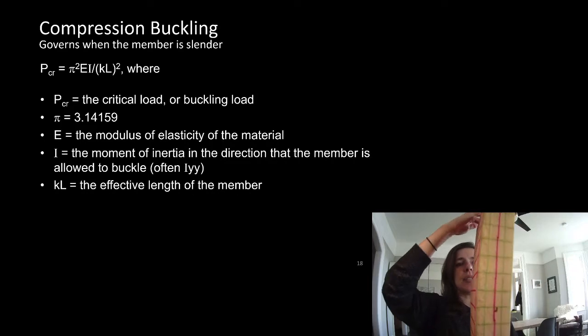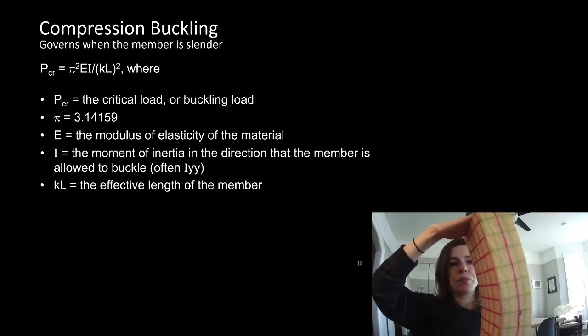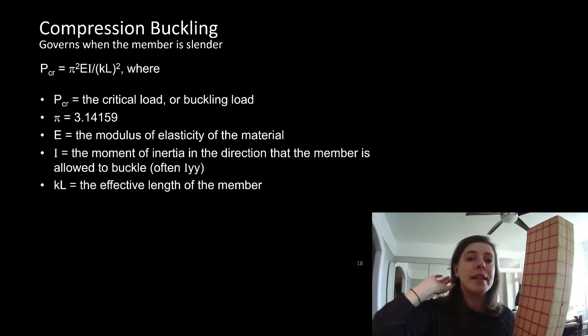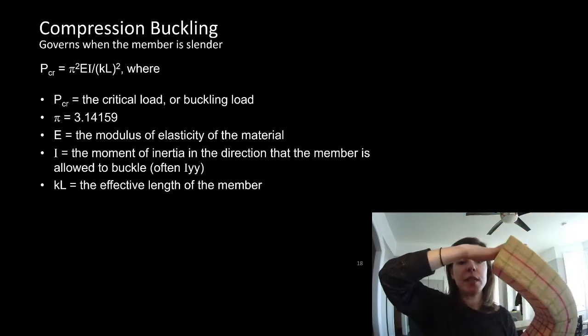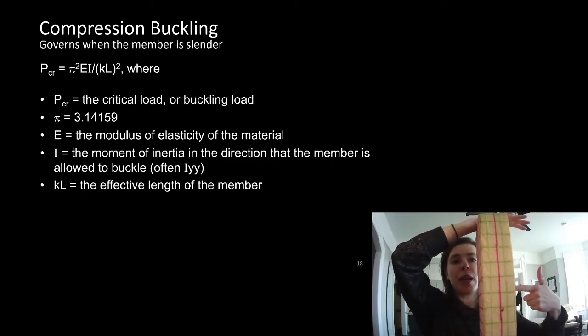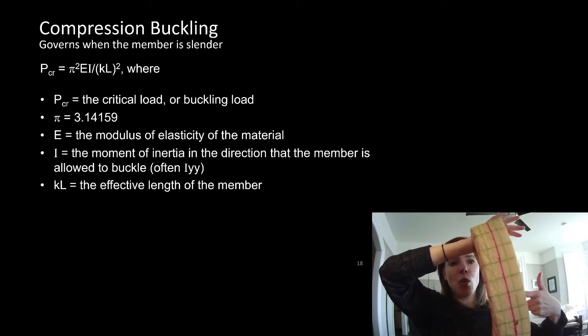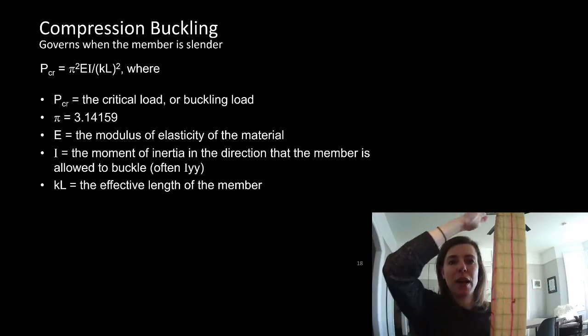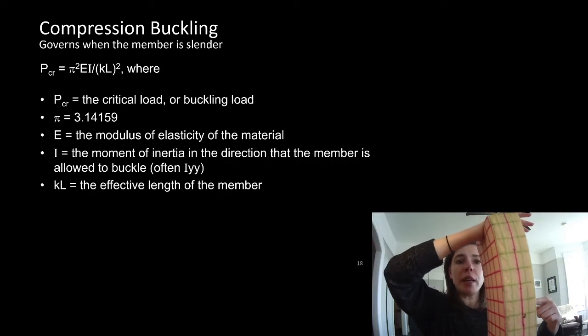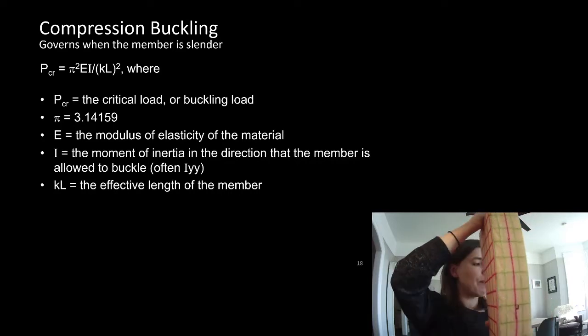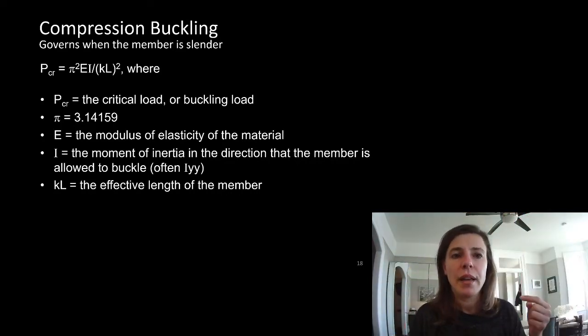Now, here's the interesting thing about buckling. Normally, live in the class, I get someone to come up and put their finger right here. And when I try to put this load on it, look, you can see how much more I'm squashing it, and it's not buckling. So halfway point, I've just stopped this from buckling, and I get people to tell me, did it feel like much force? And they're always very surprised by how little restraint it took there to stop it from buckling.